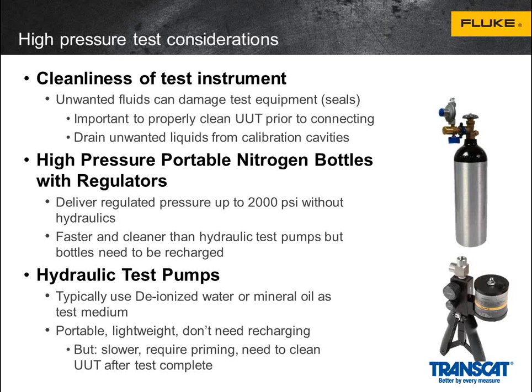If you're very, very careful, you can use things like drains and other traps in order to keep your unit clean, but it's frequently very, very difficult to do. One of the other things we'll often see, especially on things like wet gas, is that you'll end up with liquids in the calibration cavities, and if you don't properly drain them, you'll end up with strange results, sometimes unrepeatable results.